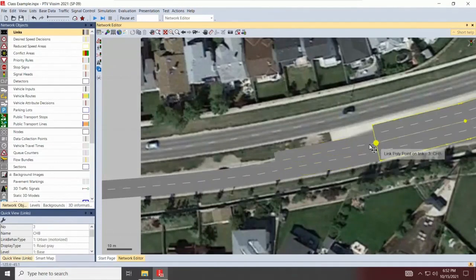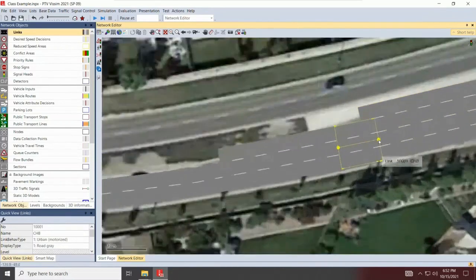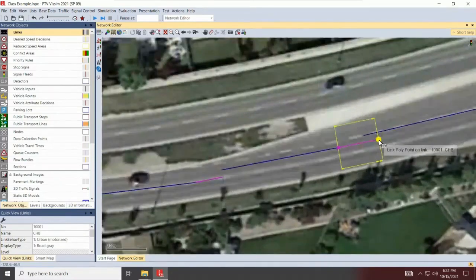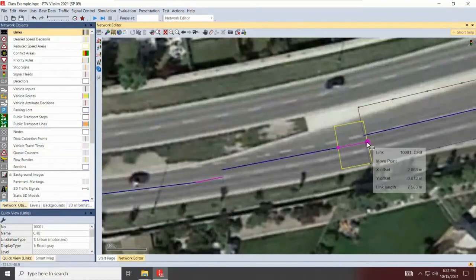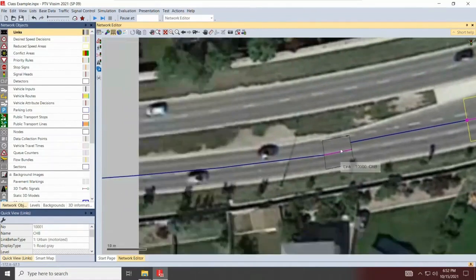And it's always nice, as much as possible, to shorten the length of your connectors. If I press Control A, try to make sure your connectors are the smallest length possible, because in bigger networks, the more connectors you have, the more time VISSIM needs to process information. Again, connectors are points where drivers and vehicles make decisions. Increasing them requires more computational capacity.